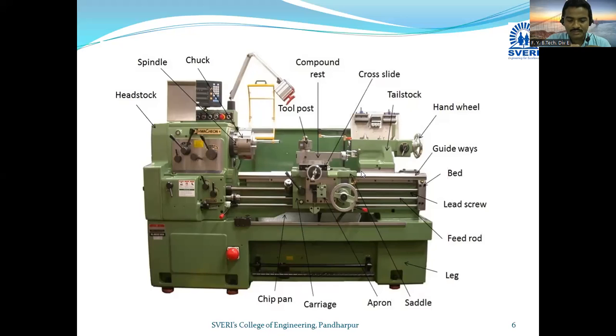Okay, because in the tailstock there is a quill. Can you see the cursor on which I have? This is a quill. In that quill, suppose you want to do the tapping operation or the drilling operation. So you can insert or press fit that kind of tool in the quill and do the drilling operation. Or suppose you want to support the job, म्हणजे ते जर एकदम लेंथी जॉब असेल, you want to support that job, so we can use the tailstock.